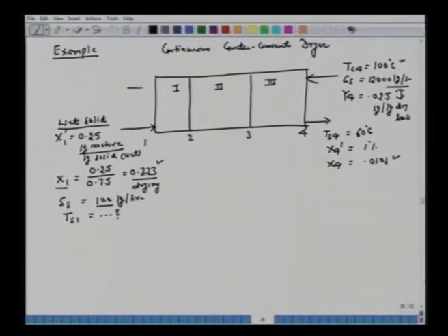Alright, so the gas which comes out has temperature Tg1 which is not known to us, it has a humidity Y1 which is also not known to us, and all this for the gas, or for the solid, we have to calculate, whatever be the temperature or the moisture content in the air phase or in the solid phase. Alright, so now when we said we have divided into three regions, the first region is unbound, the second is bound, the third is heating or post drying.